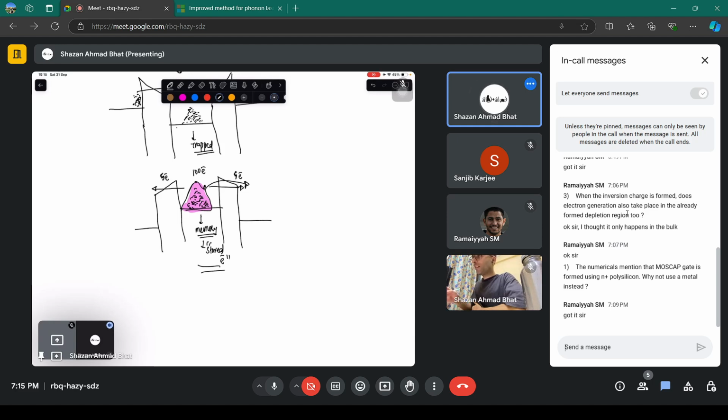There is a certain threshold value up to which, if the electrons leak, your memory will be fine. But if, let's say, 60 electrons leaked out with time, let's say in 2 years, now you have only 40 electrons remaining. Now, when you go on reading these electrons, you won't be able to retrieve your stored data after 2 years. That's why you should never leave your semiconductor memory unused.